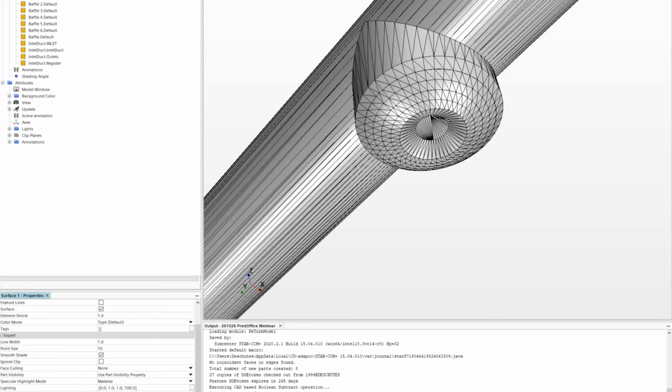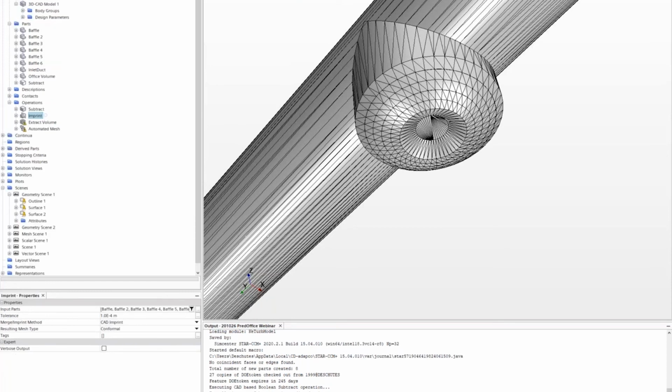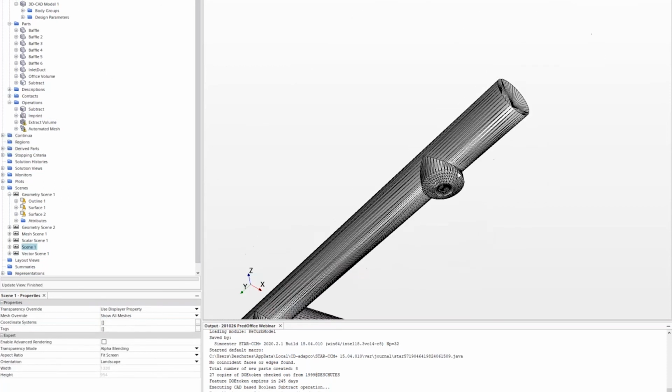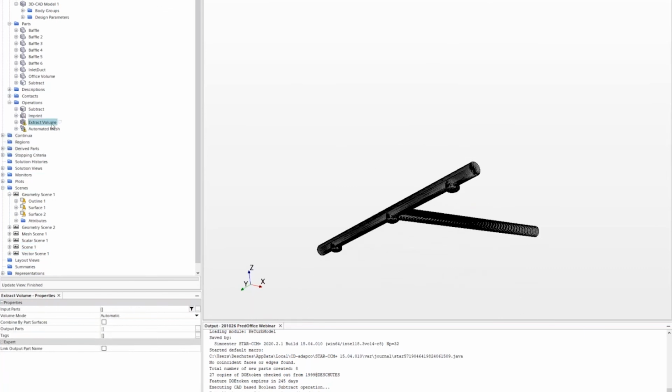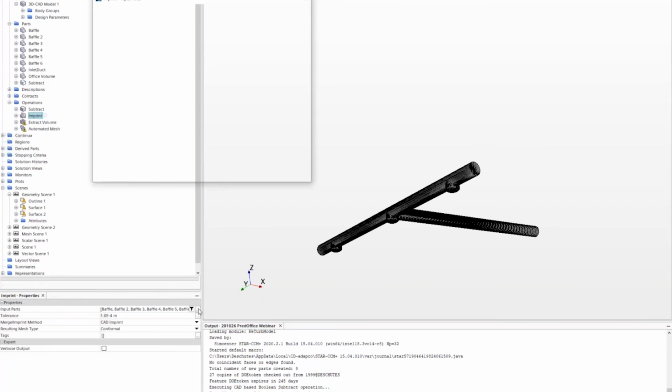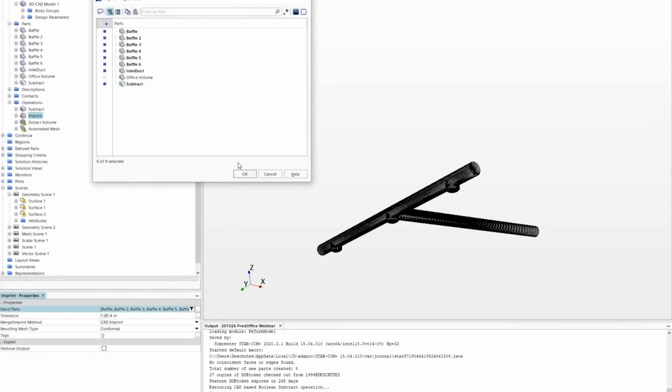This is really important especially to make sure that when we go to the meshing operation that we have an aligned congruent mesh. If you're doing conjugate heat transfers, that's an operation that you need to make sure that you have, so you're not trying to interpolate.